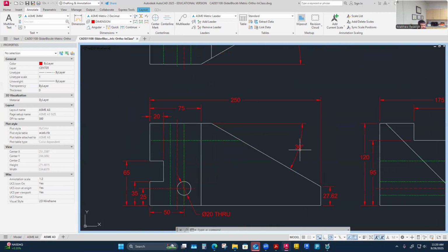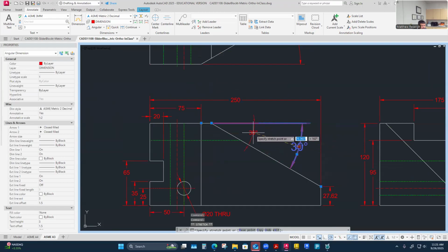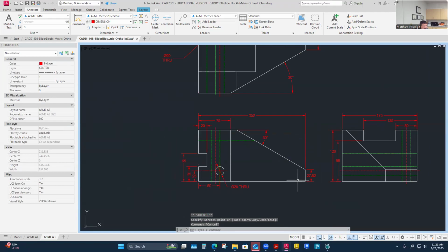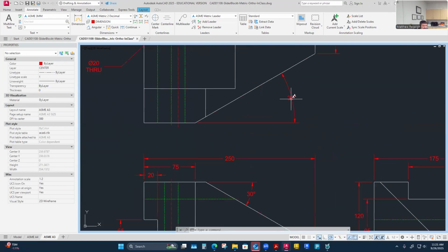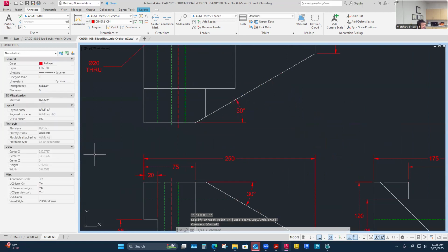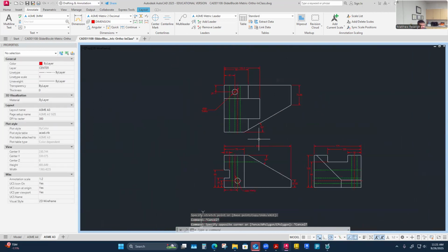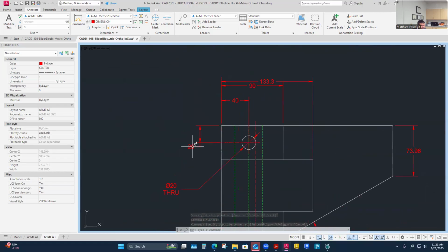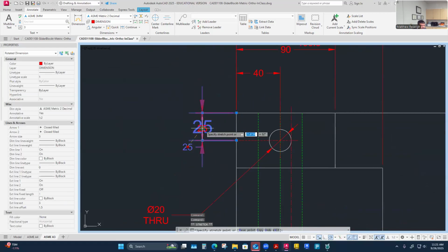And this one I'm going to probably drag in as tight as I can until it stays in between. I could let it jump out, but with my angular measurements, I like the arrows to be in if I can, and as tight to the arc as I can rather than way out here like I had it. So I'm just going to tighten this up as a preference, to keep it a little cleaner, a little less distraction. Anything out beyond that is just kind of wasted. Like this one is kind of waste, right? It's just kind of sloppy. This is better, to drag this in like that. Obviously, we'll put those in parentheses in the future when we create that dimension style, but right now that'll work. Yeah, this is going to be great here.